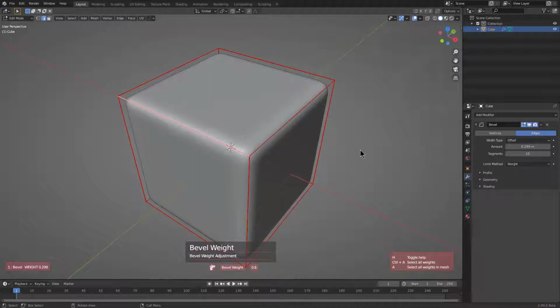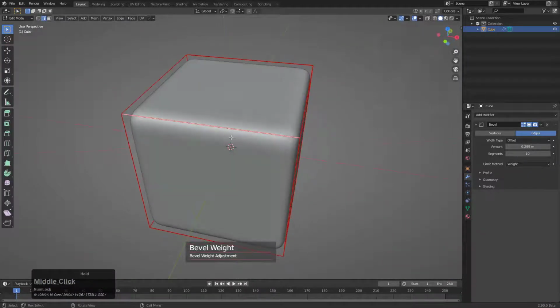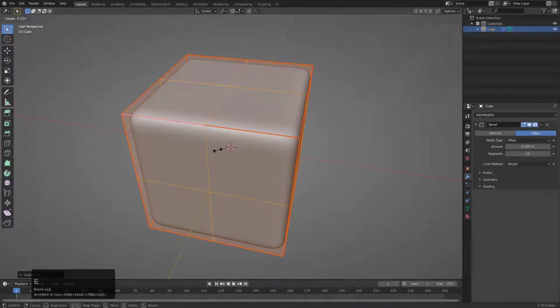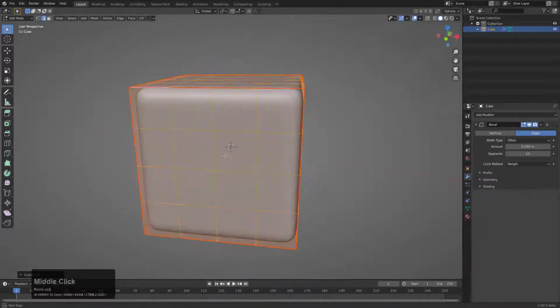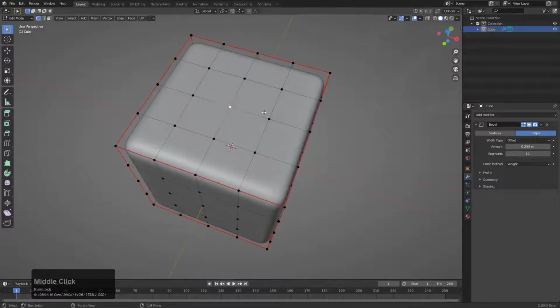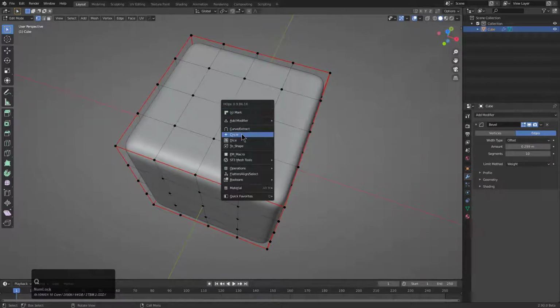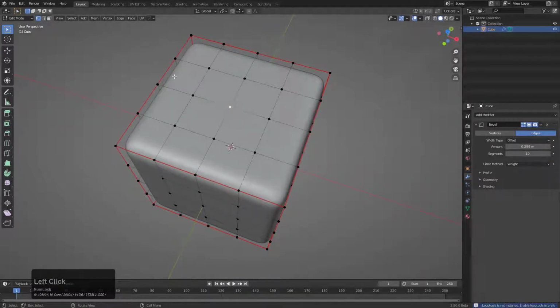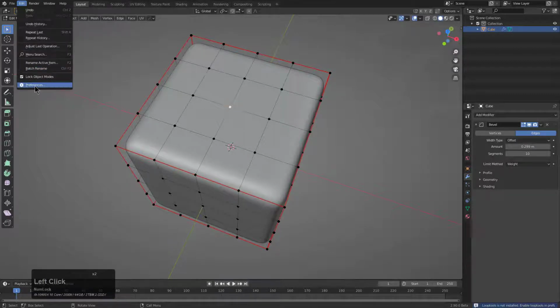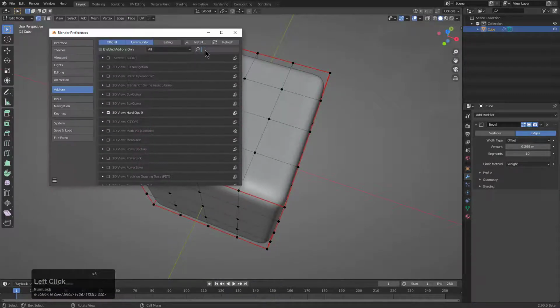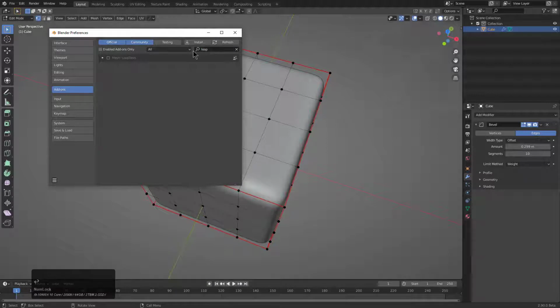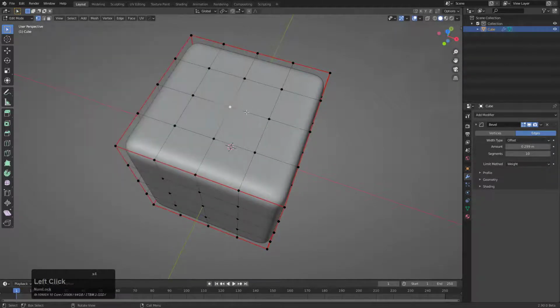So right here, it's not actually the most optimal scenario, but let's take this shape and actually subdivide it, and we'll subdivide it maybe one more time via Shift R. We'll select this vert and we'll jump ahead and actually use circle. However, loop tools isn't enabled, so let's actually go under our preferences and enable loop tools. Loop tools is a classic and it's definitely recommended, and we'll save our preferences.